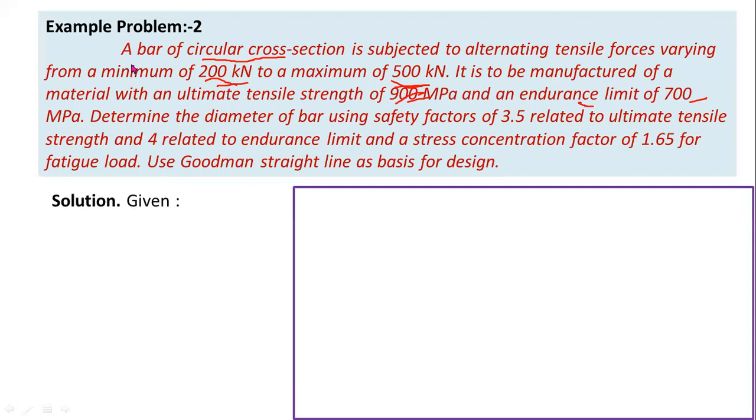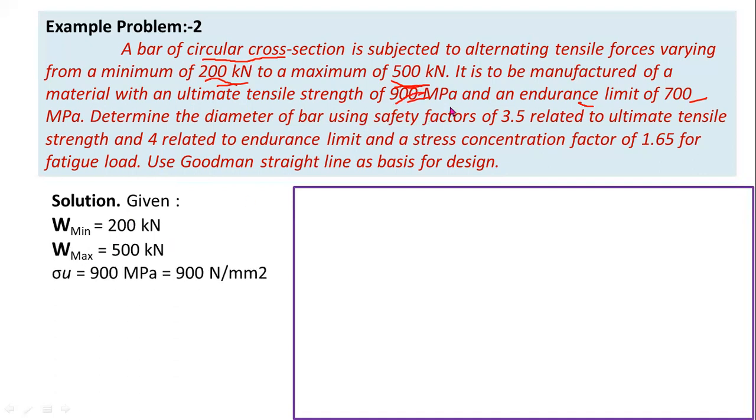From the given question, minimum load equal to 200 kilonewtons. Okay, 200 kilonewtons is the minimum load, and maximum load is 500 kilonewtons. Okay, and ultimate stress sigma u equal to 900 megapascal, and endurance limit sigma e equal to 700 megapascal.